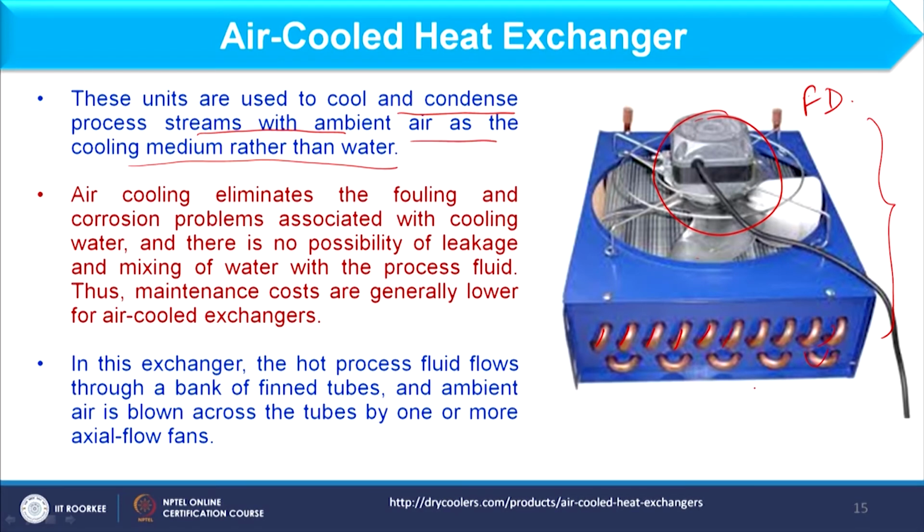On the other hand, we can place the fan at this side also instead of the top side. In this case it basically sucks the air, as it is placed after the operation. This type of fan is called an ID fan or induced draft fan, and this induced draft fan creates negative pressure in the system, whereas the forced draft fan gives positive pressure in the system.